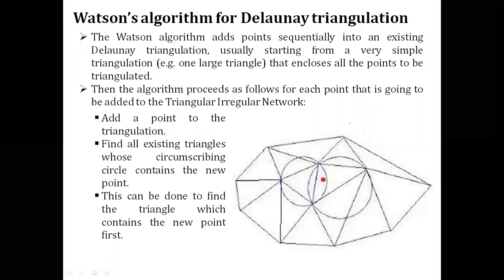The difference between Voronoi and Delaunay, as I explained yesterday, is that Voronoi gave the idea that a surface can be divided on the basis of seed points, whereas Delaunay's idea converted those seed points into your nodes or vertices, and using the smallest possible surface area, that is a triangle, they started developing the concept of triangulation.